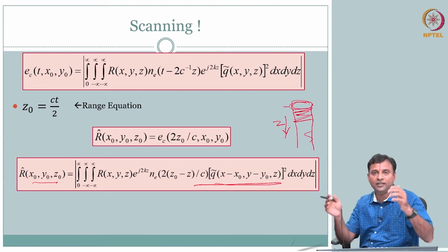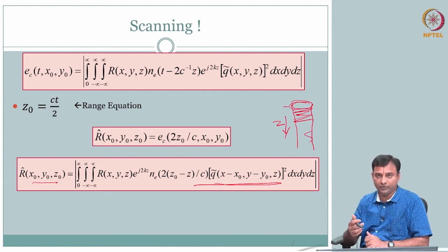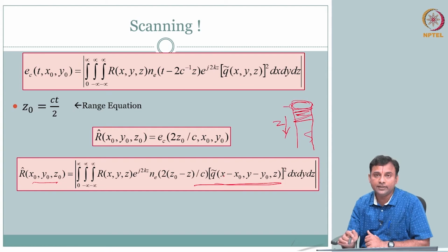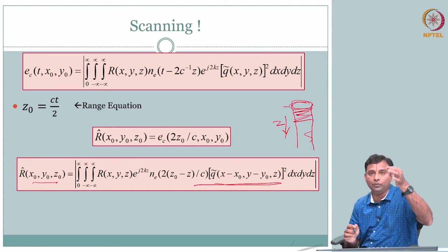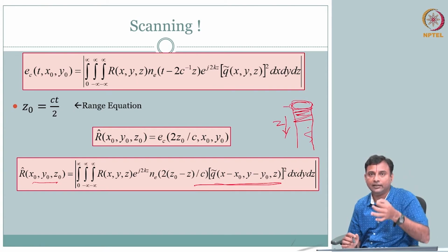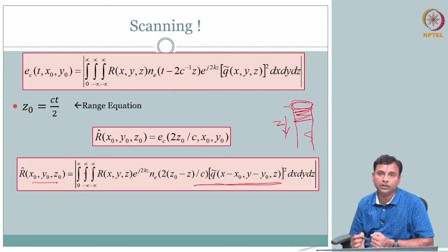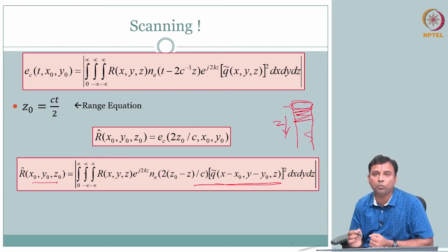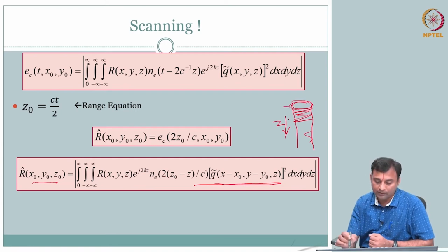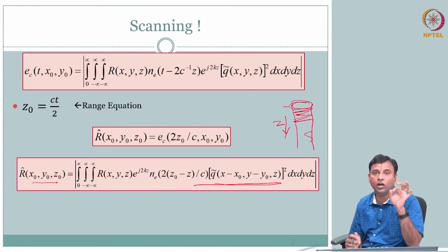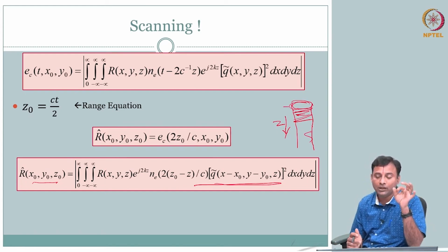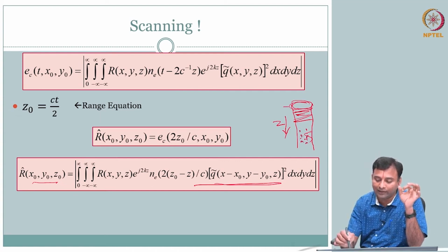so that I can avoid all this main lobe, side lobe, Bessel function or sinc function. You already notice it is a volume, a cylindrical volume. It's a cylinder. So whatever is there inside that cylinder is going to get summed. So ideally you want it to be as small as possible. Because of this triple integral, whatever is the contribution by that, we call this a resolution cell. So it is a small volume, and within that you will have different scatterers.